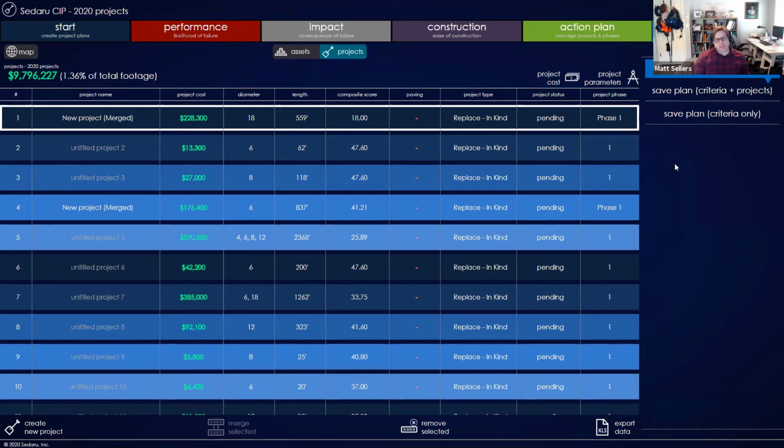But essentially, that's something that can be brought in if you have that information, like what's the % demand shortfall if this pipe goes out of service or other things. Again, we consider that most likely a custom criteria we'd bring in that needs to be populated. Yeah. So depending on how you would want to account for that redundancy, sometimes it's straightforward, sometimes it's not so straightforward.